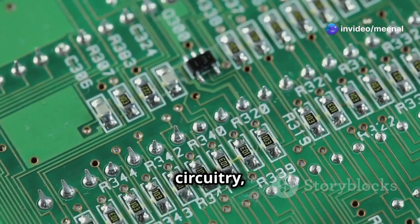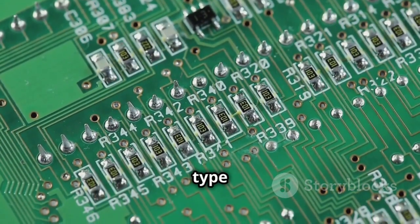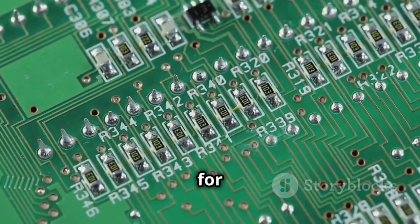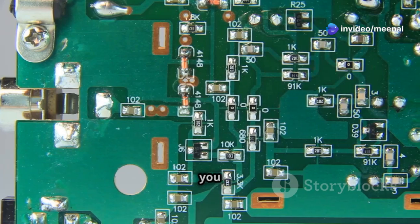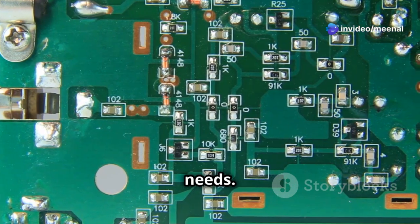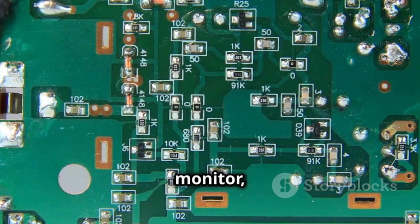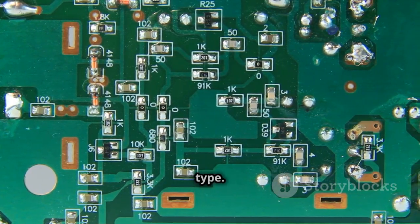In reset circuitry, one size doesn't fit all. Each application has unique requirements that dictate the type of reset IC you should use. Understanding these requirements is crucial for ensuring the reliability and stability of your system. The type of reset IC you choose depends on your application's needs. Whether it's a push-button reset, a watchdog timer, or a power supply monitor, each serves a specific purpose. Let's delve into the details of each type.